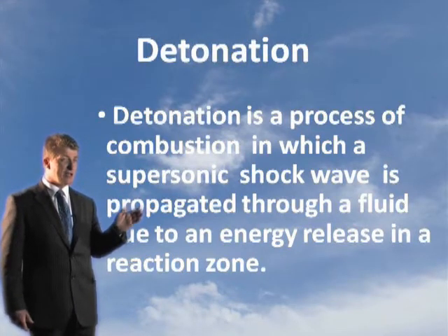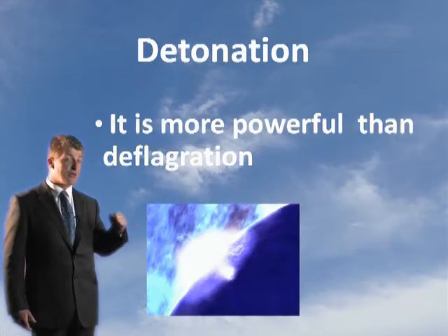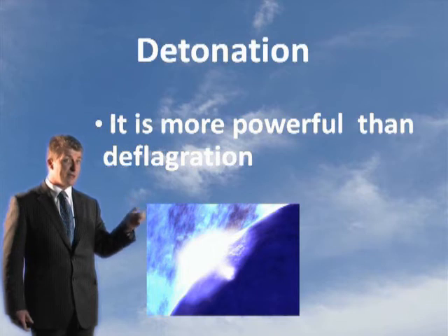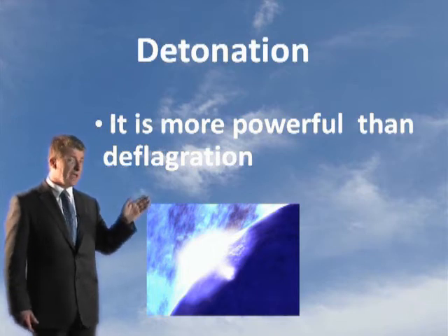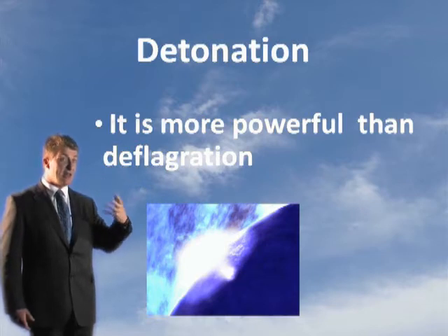Now, detonation is a process of combustion in which a supersonic shockwave is propagated. So it's not subsonic, it's faster than the speed of sound. It is propagated through a fluid due to an energy release in a reaction zone. Detonations are generally much more powerful than deflagration, and it's got a different heat transfer mechanism.